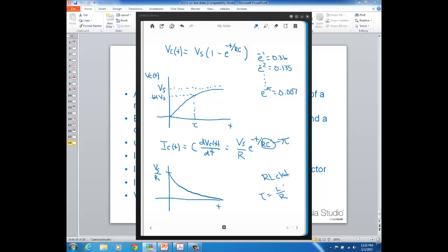And then do the same thing for the time constant of an RL circuit. Take units of L and units of R and prove to yourself that you get units of time. And then you won't get the equations wrong, and also you'll never forget that these expressions are called time constants for a good reason, because they actually do have units of time.